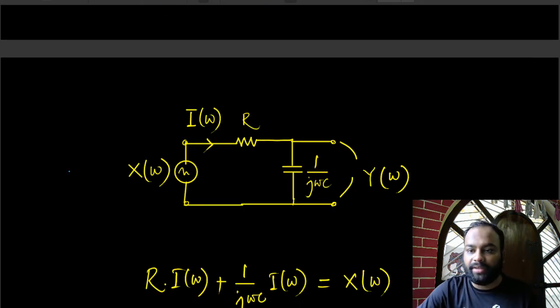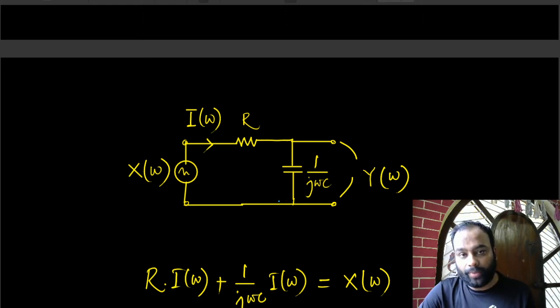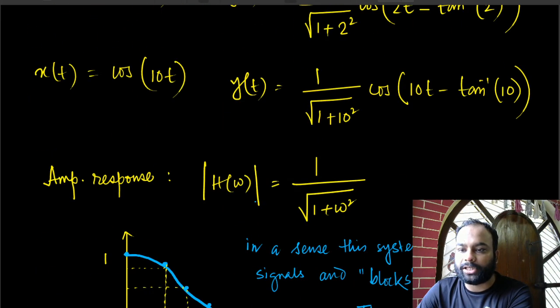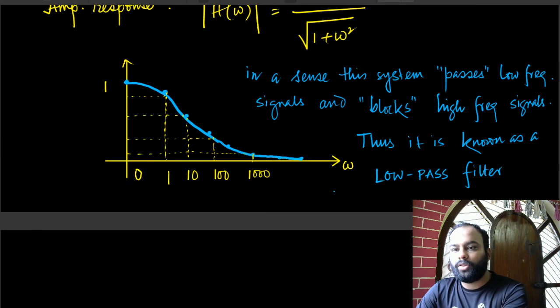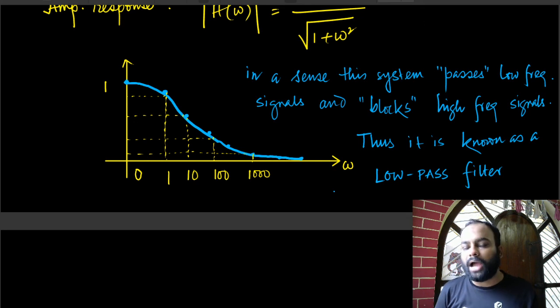and when you pass in different signals here, the lower frequencies will be attenuated less, the higher frequencies will be attenuated more, right? So that is why this thing is known as a low pass filter. So I think this idea is clear now, right? Again, we shall extend this idea later on in our next class, and try to figure out how different filters really work, how different circuits behave differently in the frequency domain. We are electrical engineers after all.